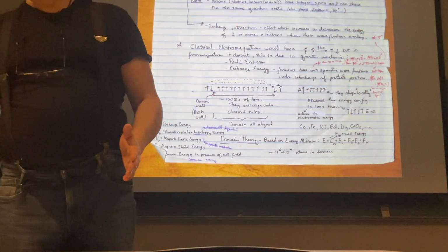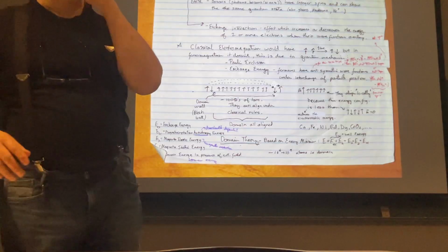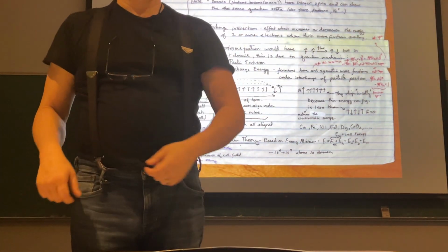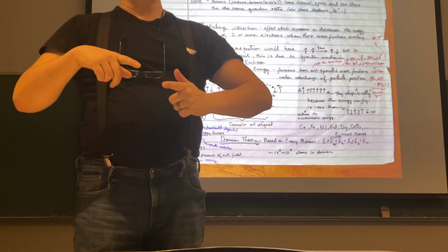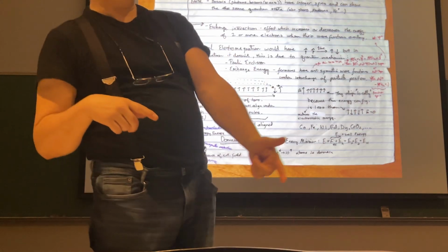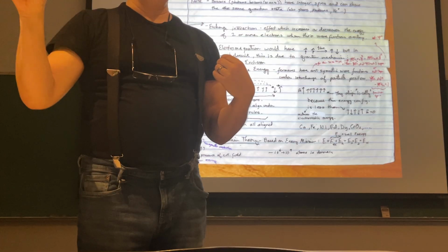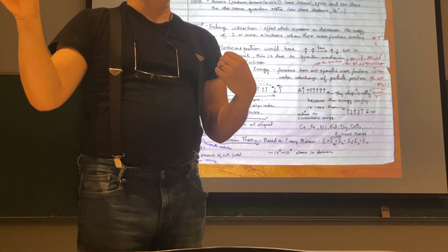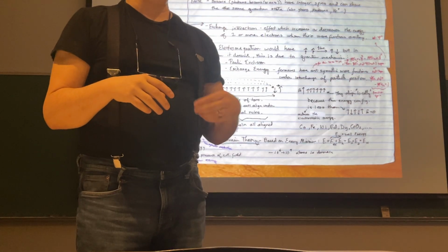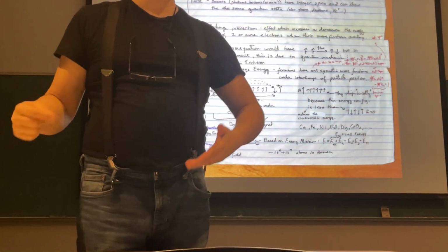Does it store it somewhere? Yeah, I mean, it will in some kind of what we call DMA transfer buffer or something like that. It saves it to some memory, but the problem is it's always the same rate of readout. And so you need one that you can read out according to a lock-in synchronization signal, which allows you to read now, a little later, maybe a little earlier than now, and keeps doing this. And if you do that, then the camera is asynchronous. It's being called to pull an image when you want it or when you need it, not just regularly at the mercy of its FPS.